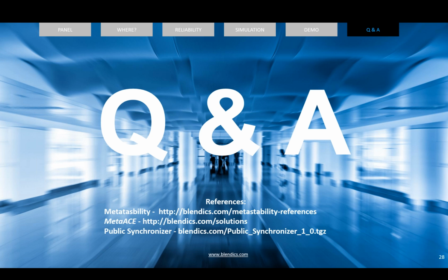Okay, and here's another question. How do I use your tool to calculate MTBF for a synchronizer in an FPGA, Dave? Well, if you're lucky enough to work at the FPGA vendor, then you can actually simulate the circuit. What MetaACE requires is running SPICE simulations. So you need to have an extracted SPICE netlist, and you also need to have the foundry models for the process that that circuit is being implemented in.